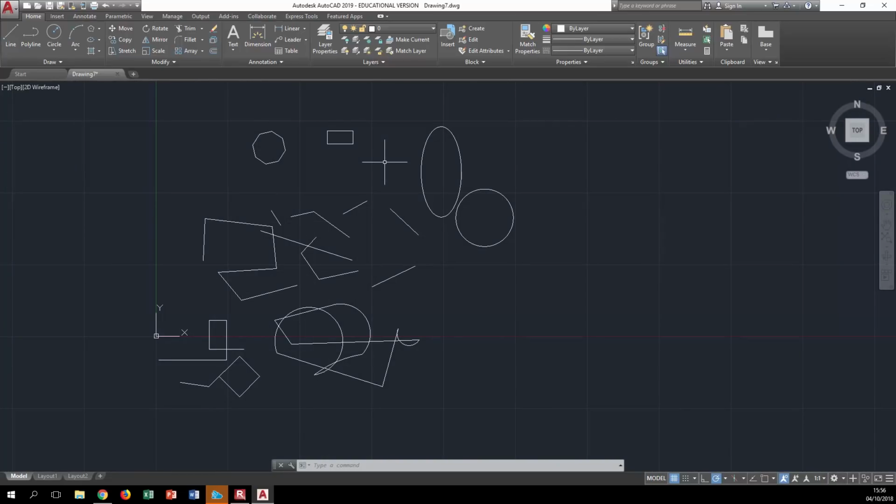Now if we go to the selection tool, if you keep pressing with your mouse, you'll be able to see this weird shape for the selection. So if you press and move the mouse clockwise, you can select only whatever is inside the shape that you draw. Like this, it will only select the polygon, even though it crossed the rectangle. However, if you go anti-clockwise, it will select whatever it crosses. So that's one way of doing it.